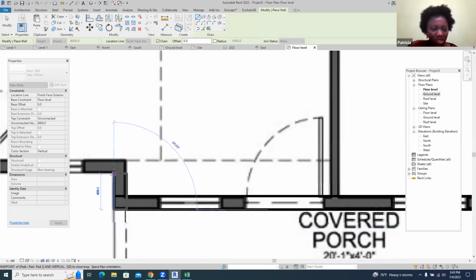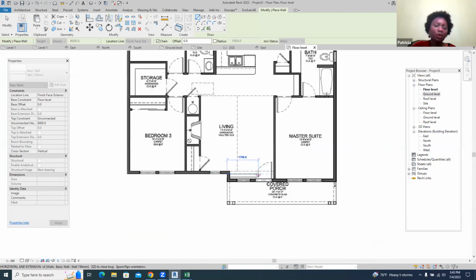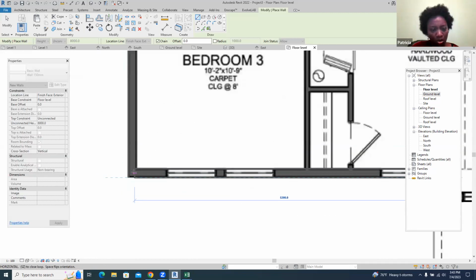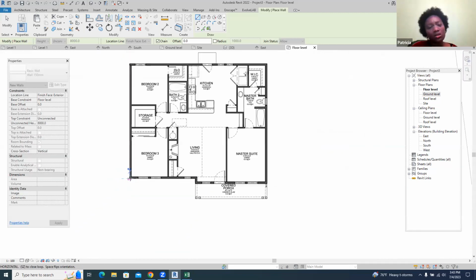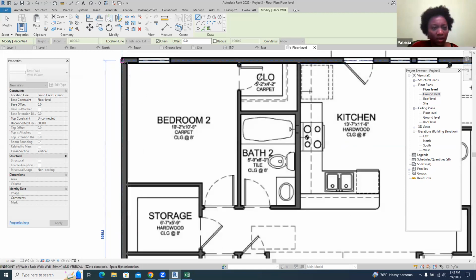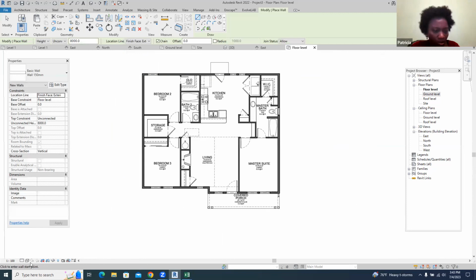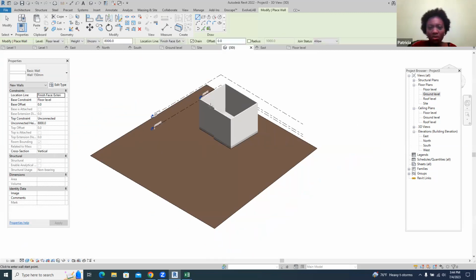If you had a sketch with single lines, you can use the single line option and then trace it out and then do your adjustments on it. So I have the outer walls for this. If I come here, let's say Shaded, and then want to see its realistic view, for every view you can set how you want to see it. I think the shaded one showed us more. And then if I go to the 3D view, it's showing me what I have here.